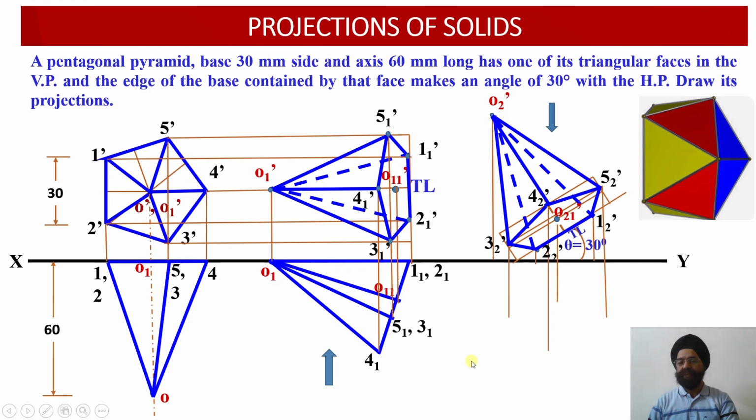Wherever these vertical projector lines intersect with the horizontal projector lines which we are going to draw from the previous plan projection view, the points of intersection of the corresponding points will provide us with the location of the 7 points in the plan projection view. So let us start with point 4 1.